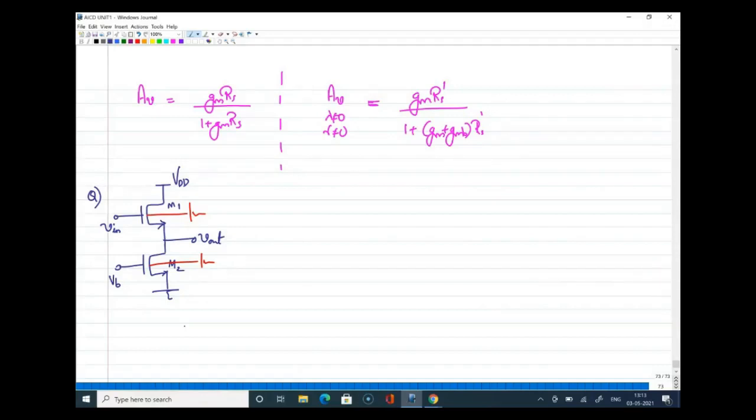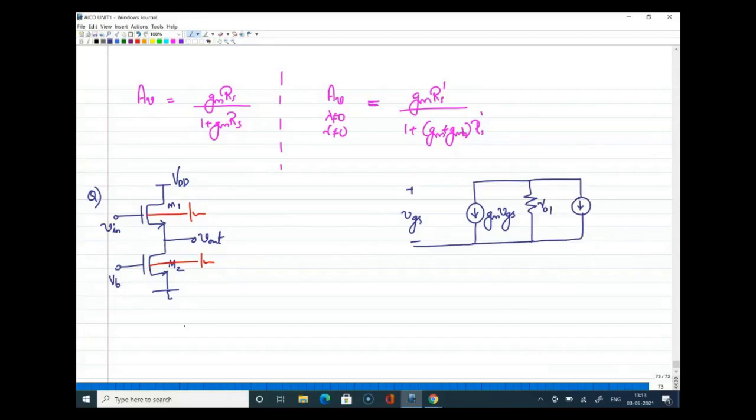Okay. So what we do here is we'll proceed with the same equivalent circuit, and let's see how we can write it. The top M1 is our input transistor. So I'm replacing the input transistor with its equivalent, which is GM VGS, with a VGS voltage plus minus here, and that should be continued by the R naught of that, R naught 1. And one more thing is the GMB VBS of that. This is for the input device, and this point is grounded.